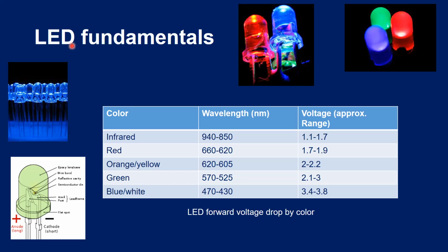So it's simply a PN junction in semiconductor theory, and we know how the diode works. It's a PN junction. It has two terminals such as anode and cathode. However, this special diode emits light when it is conducting a current through it. Okay, so when it is forward biased, it emits light, and it emits light in different colors. So we will see, when it emits a particular color of light, what is the science behind it.